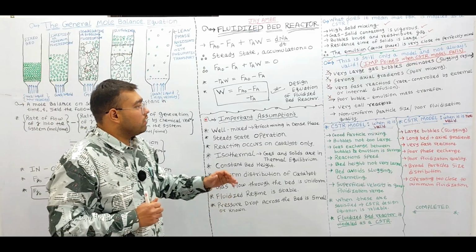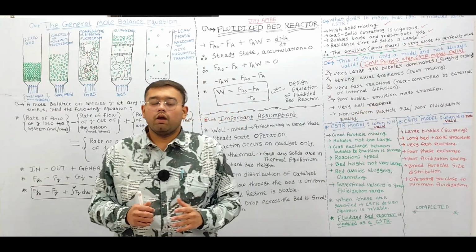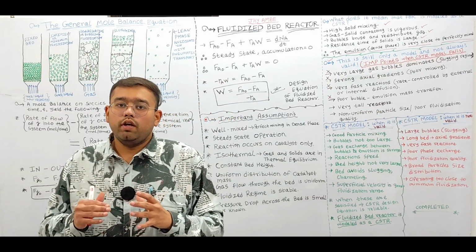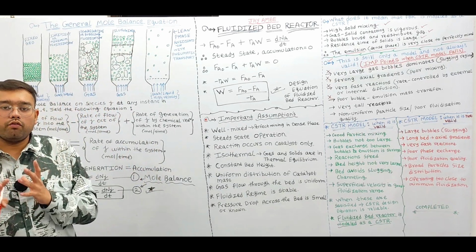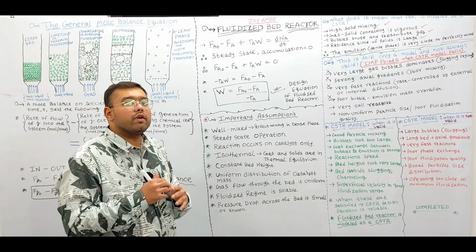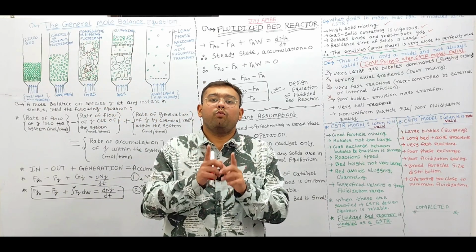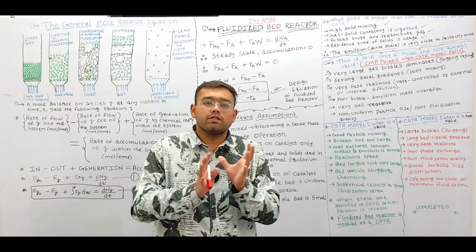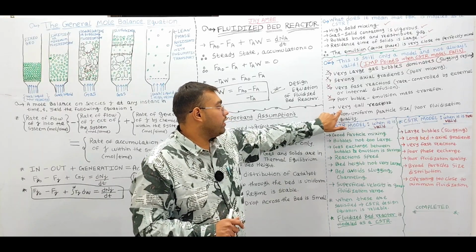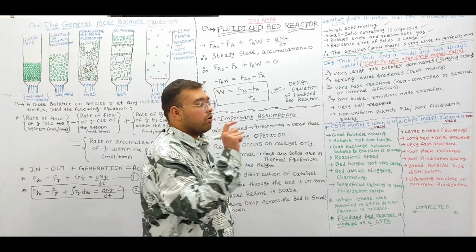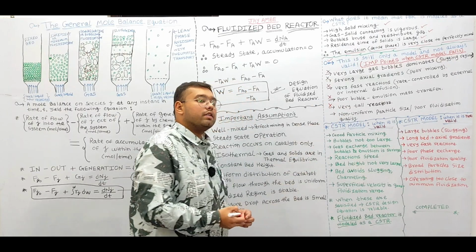So when we have very tall reactors, the solid phase will behave as a CSTR and the gas phase will behave as a PFR, which means we will not have a uniform CSTR. We'll have a mixture of the PFR and the CSTR. So due to those reasons, during these conditions, we cannot model the fluidized bed reactor as a CSTR.